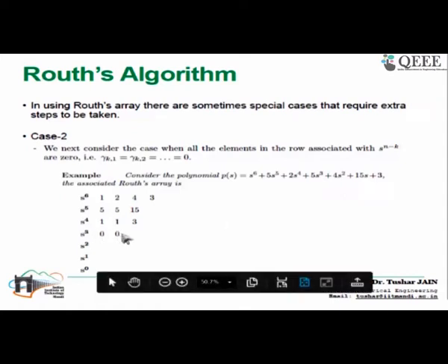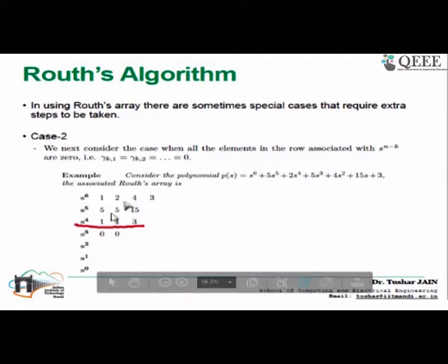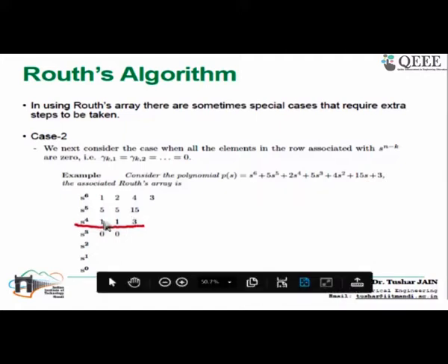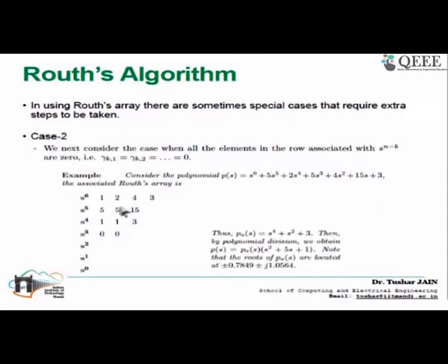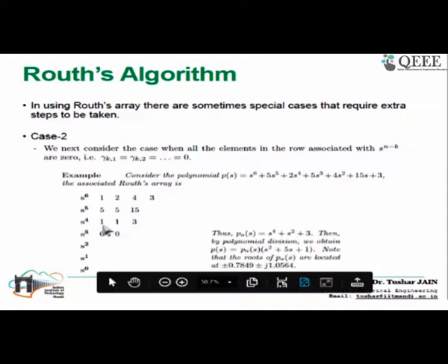So you go one row above, that is to say this one, and write a polynomial with respect to this row. The leading order of S would be 4, and it would be alternating as well, meaning for this one I will have S to the power 4 plus S square plus 3.